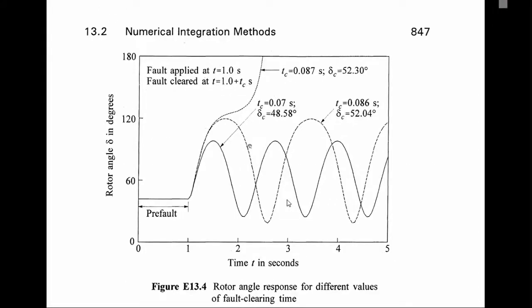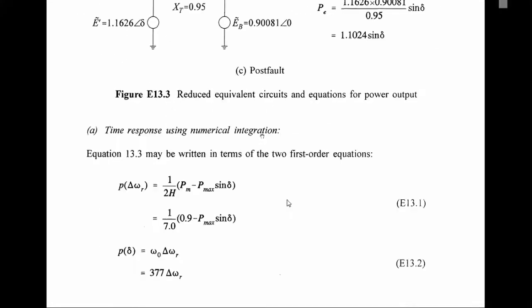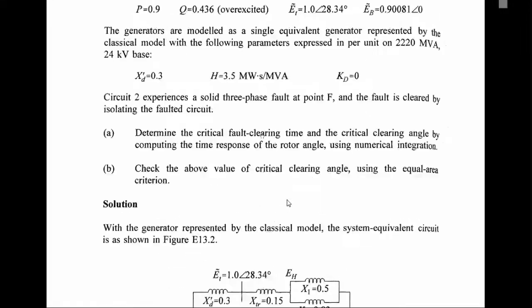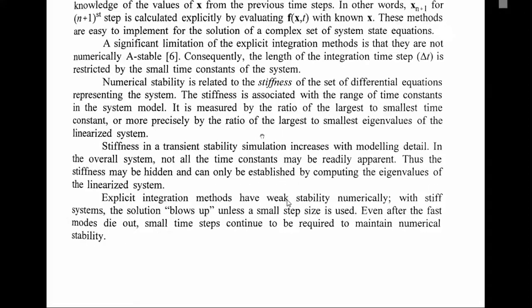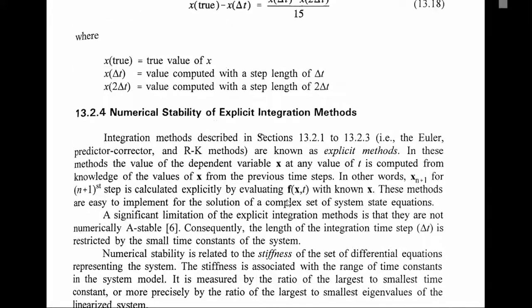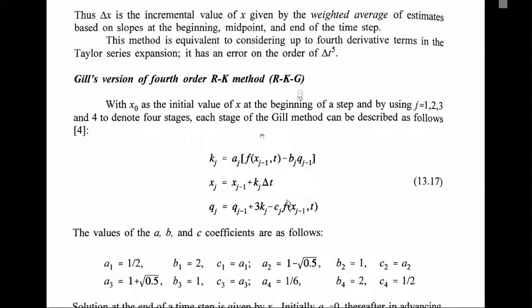So this is the information that we require to plot this graph. We want to replicate this graph and see the critical clearing angle for various clearing times. But to model this, let's look back at our swing equation, and then we will solve this swing equation in Simulink.